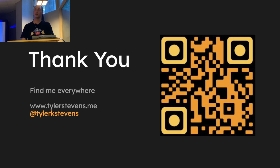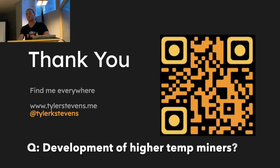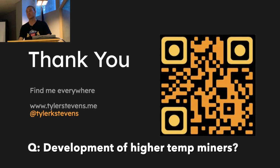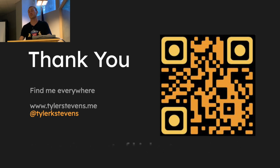The chip temps operate higher, but every aspect of the whole electrical design has some kind of temperature rating. One example is S21 chips. The main firmware will shut the whole machine down if a single chip hits 100 degrees C, and then it's off. Yep. So that's kind of the limit on the new gen right now as we know it.